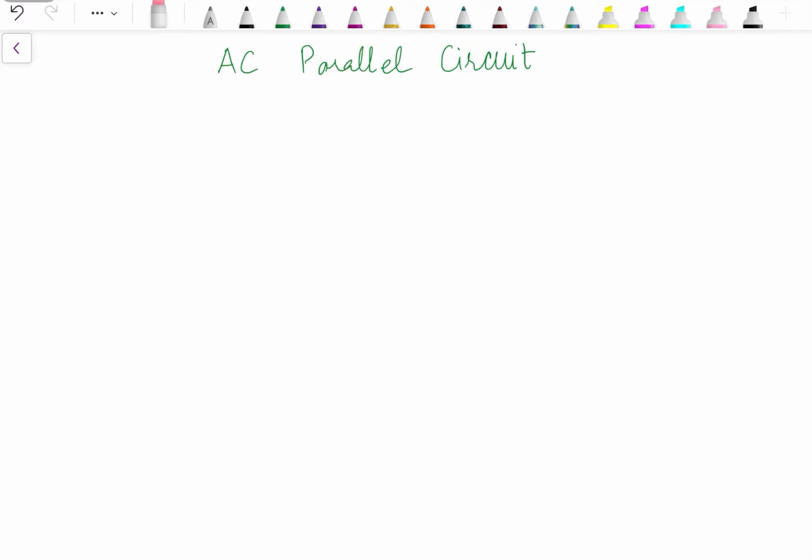This video is about the AC parallel circuits. In the previous videos, I had taken the examples of AC series circuits, and what we had seen in AC series circuits, the current through each of the circuit elements remains the same, while the voltage across the different circuit elements which are connected in series is different.